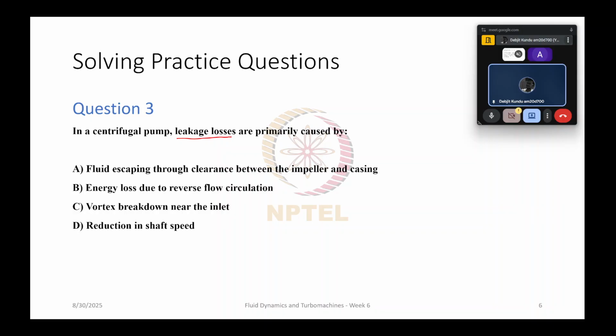A few of them that I can think of right now off the top of my head: from this week, it's these velocity triangles and how to use them to solve problems. Then another part would be finding the total to total, static to static, and static to total efficiencies in turbomachinery. For that, you need a little bit of thermodynamics, so that either the temperatures or the pressures would be given, and you have to find the other variable.